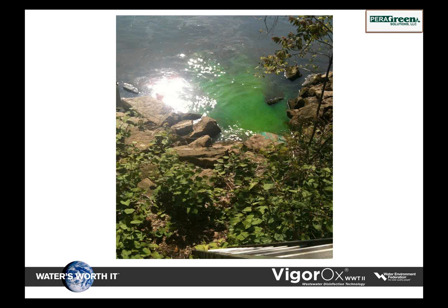chlorine residual, which is the same test you would use for PAA with a different multiplier, but see what that is in the plume and outside of the plume. Well, we tested the plume, and it was very similar to what we saw, 0.3 parts per million. We went 25 feet upstream and got 0.25. We went out into the middle of the Ohio in a boat and got 0.3.